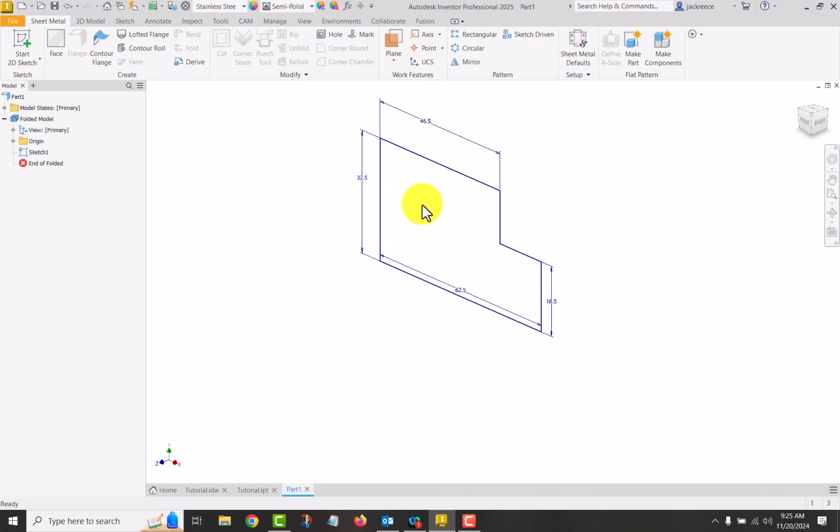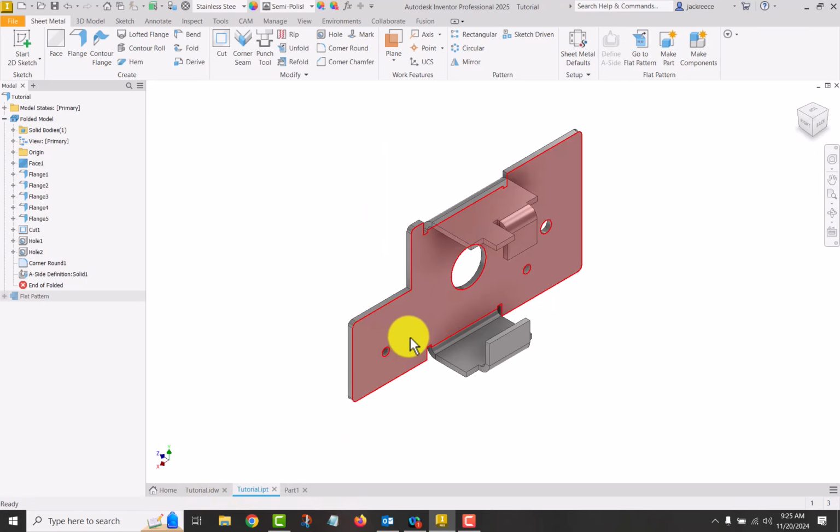And everything after this first face that attaches to an edge that's coincident to it, a bend will be created from there. And what I'm talking about, let me come back over here. So this is my base face right here. This was another face that was created coming out, and the program creates the bend that goes with it.